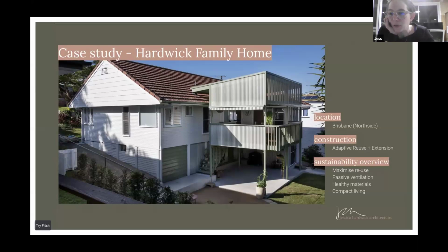And then of course thermal mass. At the farm, by having a concrete floor and a really well considered passive response, we make sure that the concrete is heating up throughout the day in winter, allowing that stabilization of temperature into the nighttime.